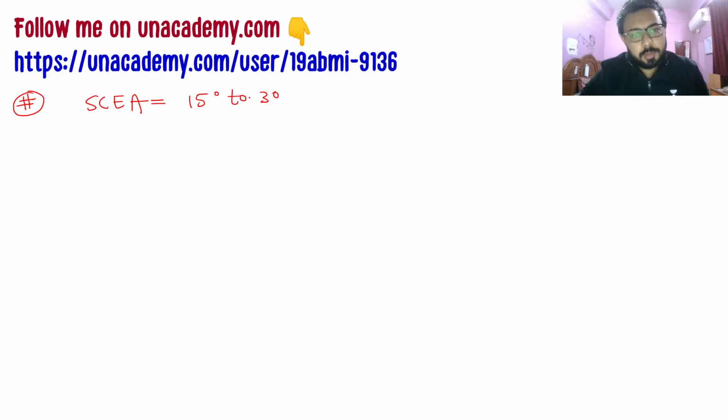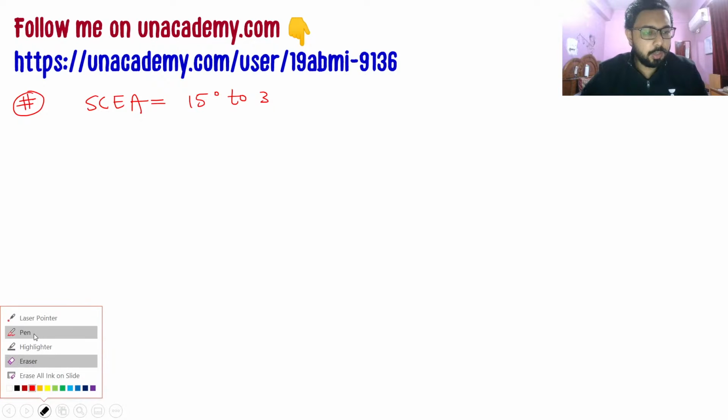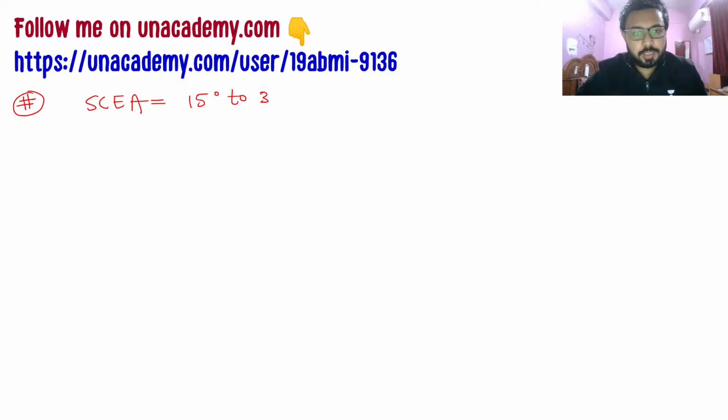So just remember that this is very important that I am discussing this value, because when you get tool signatures, that signature will have this side cutting edge angle and other angles. So you can just know if the tool signature is not clear, whether it is ORS or ASA. I will talk about the tool signatures in the upcoming slides.